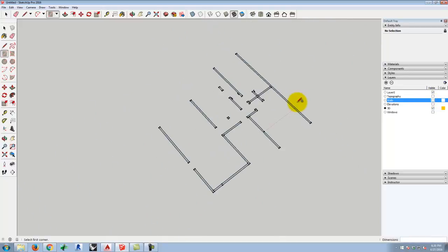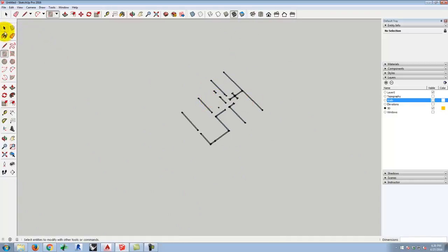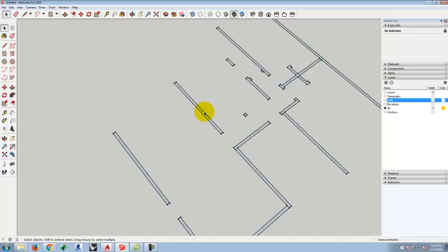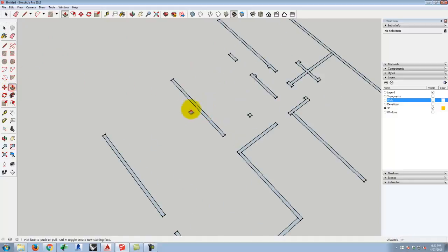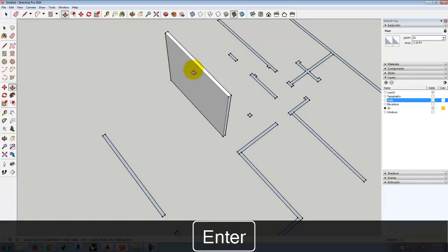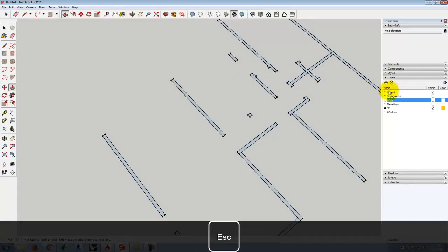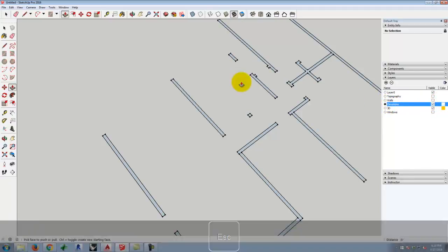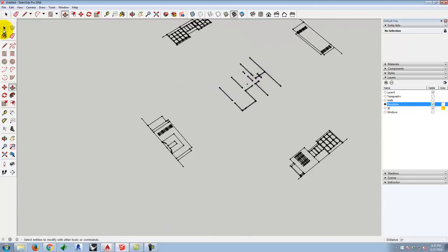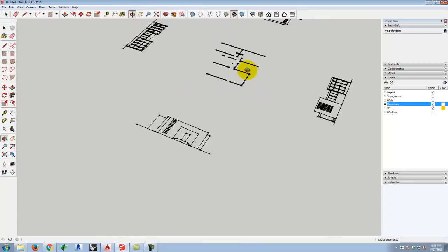And now it's going to be time to extrude those walls up into the third dimension. Okay? Obviously I designed this building, so I could just use the push-pull tool and say, oh, this wall needs to be 12 feet tall, for example, and I can draw it that way. But sometimes it's easier to reference the elevations that you've already created. So I'm going to show you how to do that. So my floor level right now is right here on the ground plane.